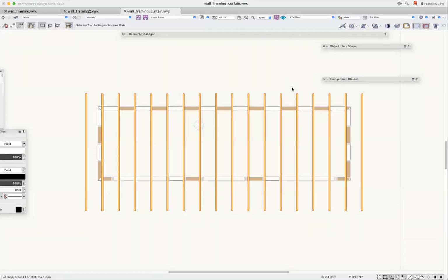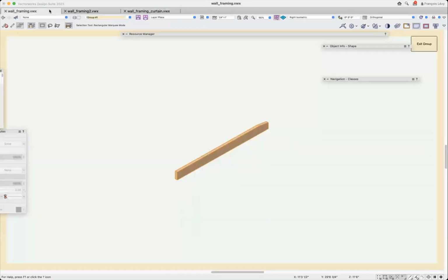So you can't make an auto hybrid out of a hybrid. But if you dehybridized that framing member by clipping part of it with subtract solids or add solids, like I did back over here, even though buried within that subtraction there is a framing member, you can create an auto hybrid out of that. So it's a bit of a workaround.